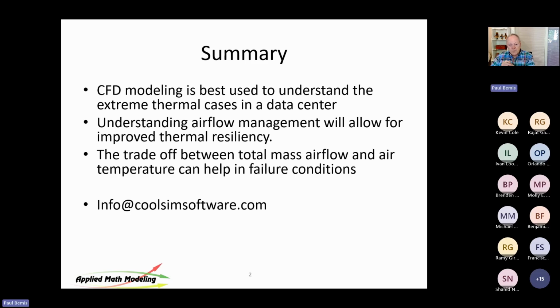And when I went to the roof to see where their heat exchangers were, they were sitting on a hot black roof in the sun. And so I measured the surface temperature of the roof at 165 degrees Fahrenheit. And what happens, therefore, is the intake temperature to those cooling units goes up. And with high intake temperature on the cooling unit, you have cooling capacity problems, okay?